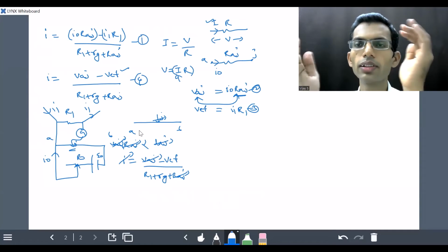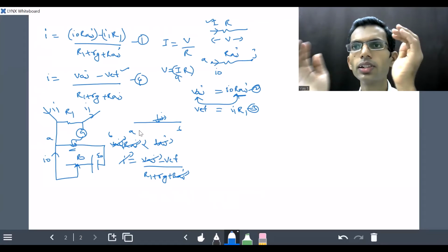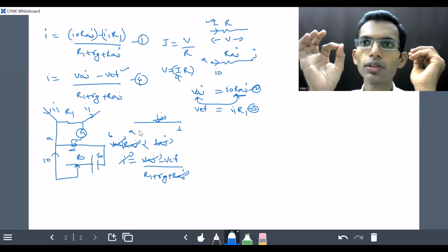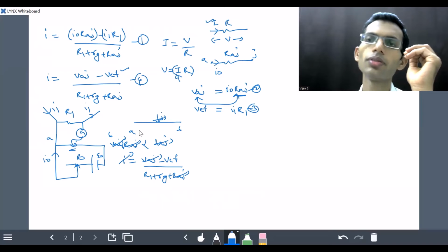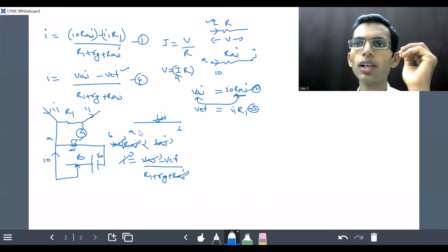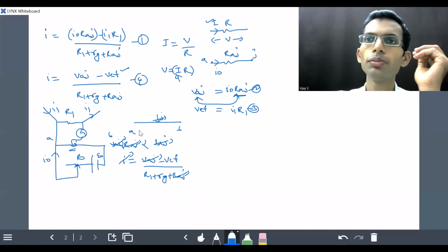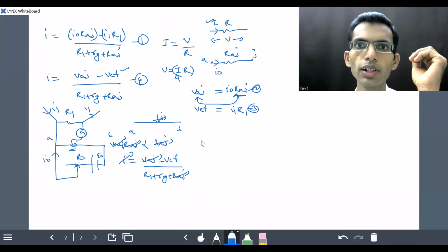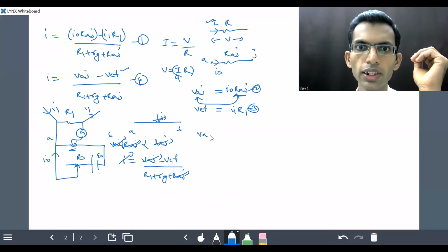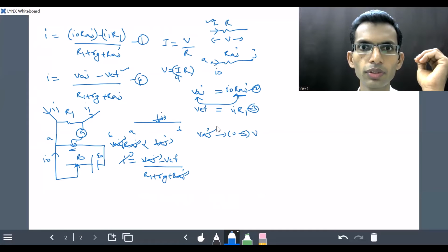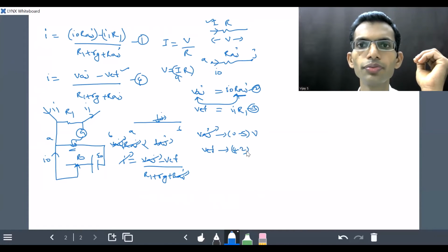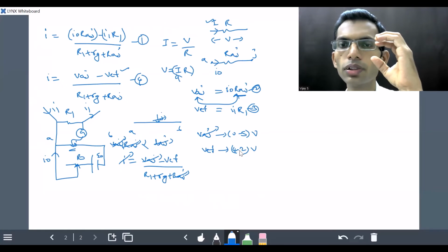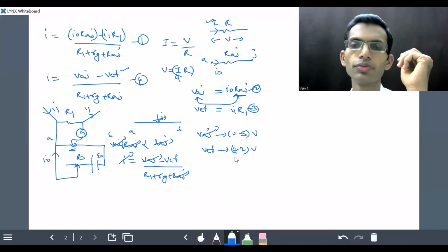Here VAJ is varying. So in the range of variation of VAJ, our objective VF is going to be present. Of course, they design it like that. Let me make it clear through an example. Let us say when you move the moving contact, VAJ is varying from 0 to 5 volts. Let us say the VF value is 4.2 volts. You can see 4.2 volts is present between 0 and 5 volts.